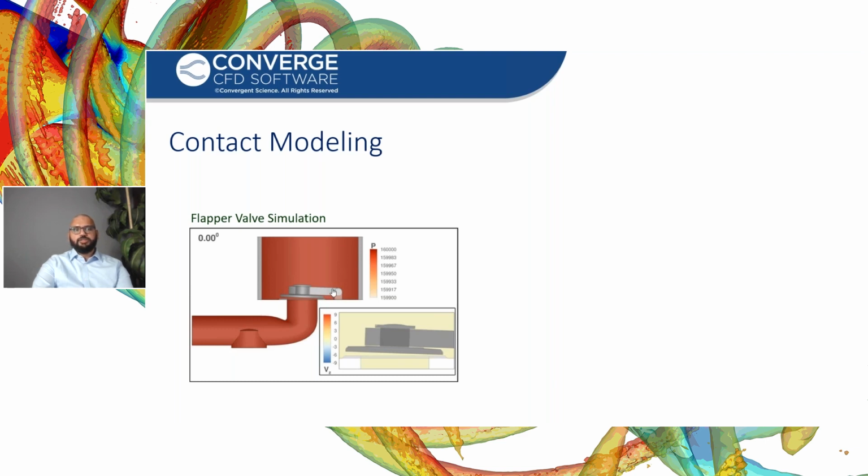So the valve could be rigid or deformable. In this example, you have a rigid flapper valve. As the flow comes in, the valve tries to rise up. It is constrained by the stopper and the shaft, and so it kind of rattles in place, and you have this complex interaction between the valve seat and the valve stopper. And you can see how the contact model is able to capture that feature, and also how CONVERGE is able to handle the flow in these thin gaps.